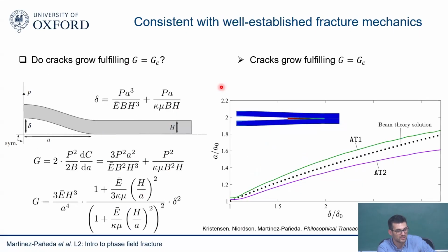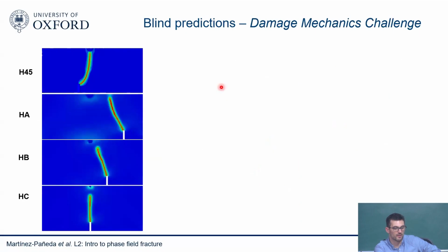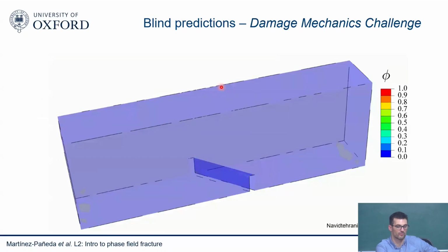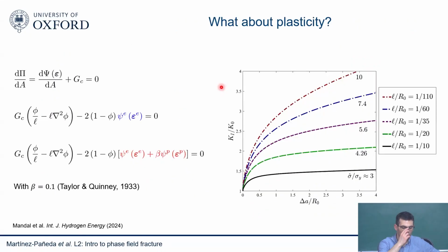However, in an elastoplastic material, we know that metals exhibit a rising R curve, right? So the toughness is not constant. If I plot applied K versus crack extension, this is what we call crack growth resistance curves, R curves. The cracking starts at K equal to K1, but they don't grow straight away. If you plot an experiment, it will be the same, right?